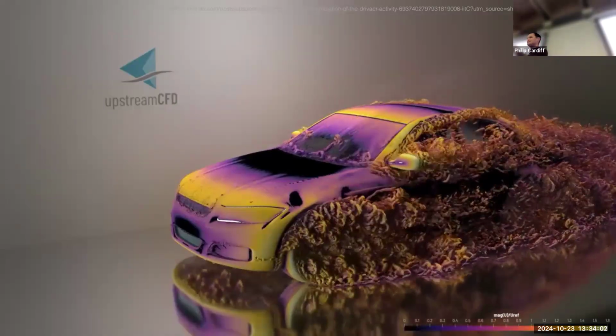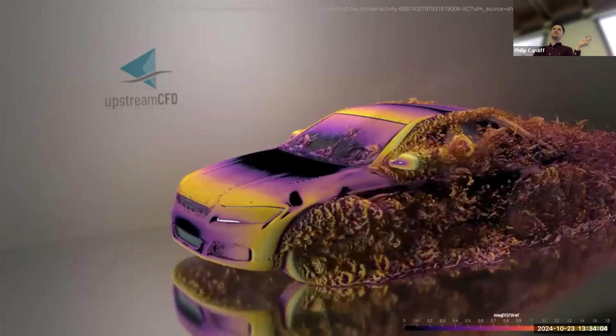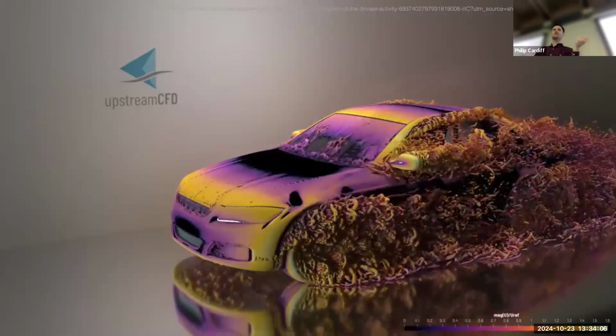If you look at this, the mesh is not 10 microns, but it's definitely millimeter scale. So this will already have probably 100 million cells in it. But you can imagine this will give very precise lift and drag. Car companies care about dropping the drag, fuel efficiency, etc. So maybe they can play with changing the shape of this and run this. Still, your average Audi engineer is not firing out an LES simulation every day. This is something where they have a specialized team that will come in and do it. But the RANS simulation is something they could do every day.